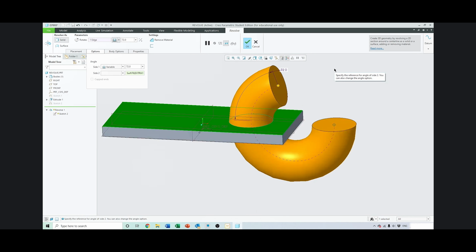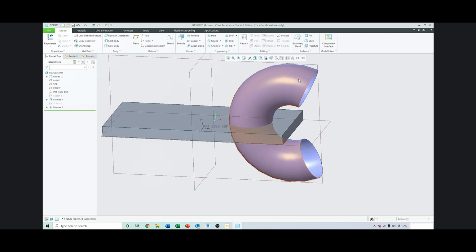And you'll see that this edge is now snapped to this surface. If I wanted to, I could have this revolve symmetrical from the first sketch. To do this, again, in the Options tab, side 1, let's just go for symmetric, and you'll see that I can now drag this, and the revolve will be symmetrical around the sketch. Let's change this to surface and accept. Again, see the difference between a solid part and a surface. Solid is shaded in grey, a surface is shaded in blue.